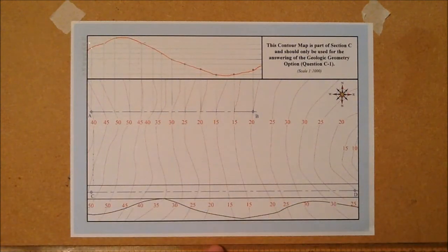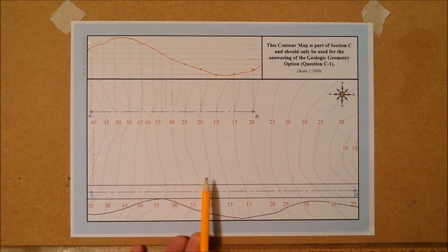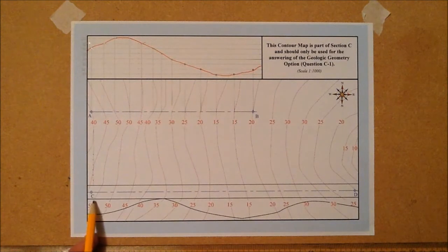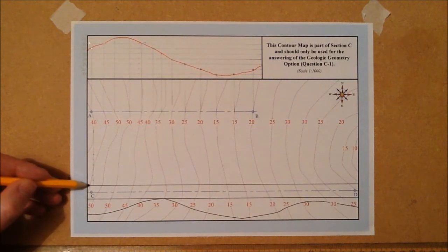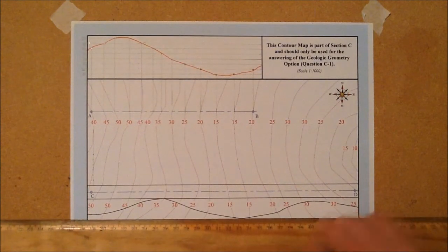So if the road itself is at an altitude of 35 metres, okay, we need to look and see, is the rest of the ground around it higher or is it lower? Okay, so this may vary in different parts. For here, I'm going to see a part C, so you're ranging between the contour of 45 and 50. Okay, so if on this place, this contour here is at a level of 45. Okay, I'm just going to start measuring out my lines and draw the level of the contours here.